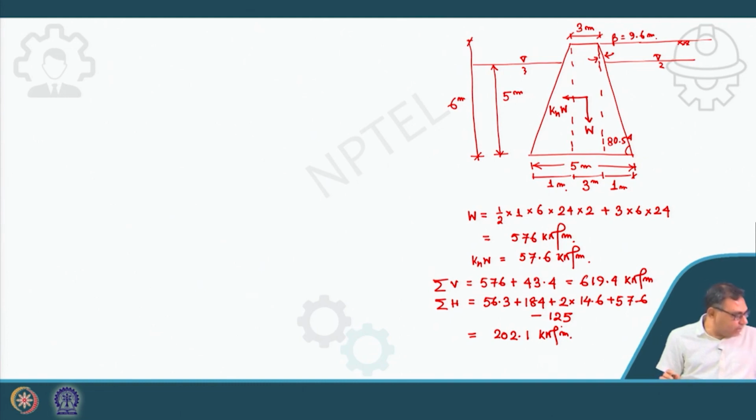Okay. So, now I will again calculate. As the factor of safety against sliding was already safe for 3.5 meter width, definitely it will be safe here also. So, no need to check. Even the factor of safety for overturning moment will also be safe here.